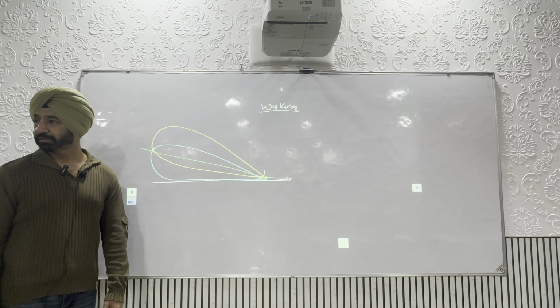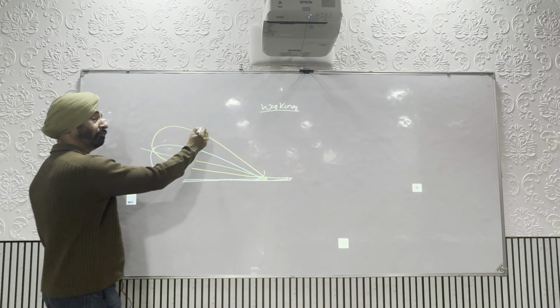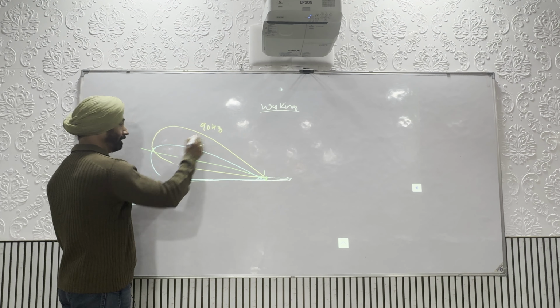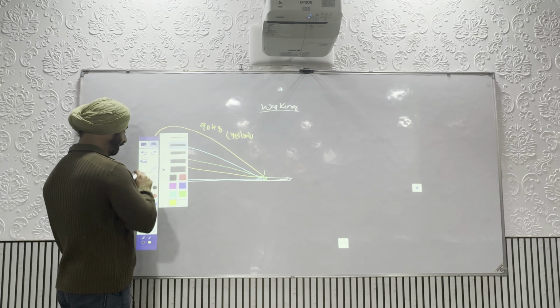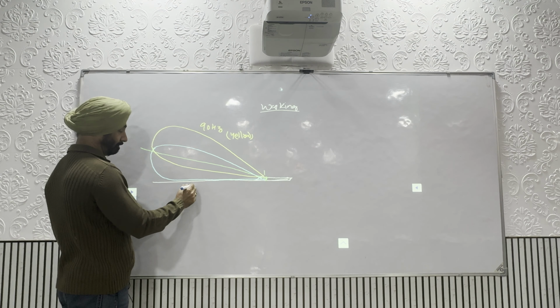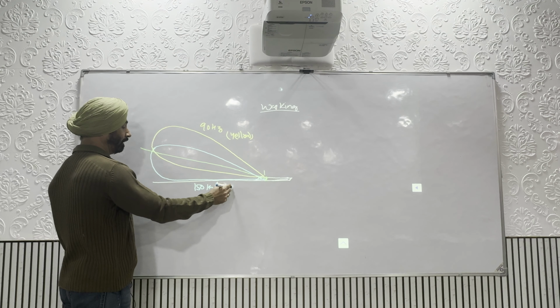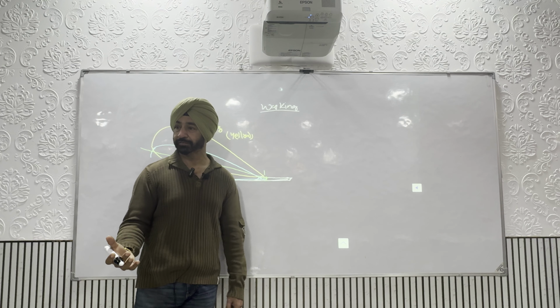What information is there? It is a radio signal. This is 90 hertz and named the yellow lobe, and this is exactly the same, 150 hertz, the blue lobe, but they do not interfere with each other because the carrier frequency is different.